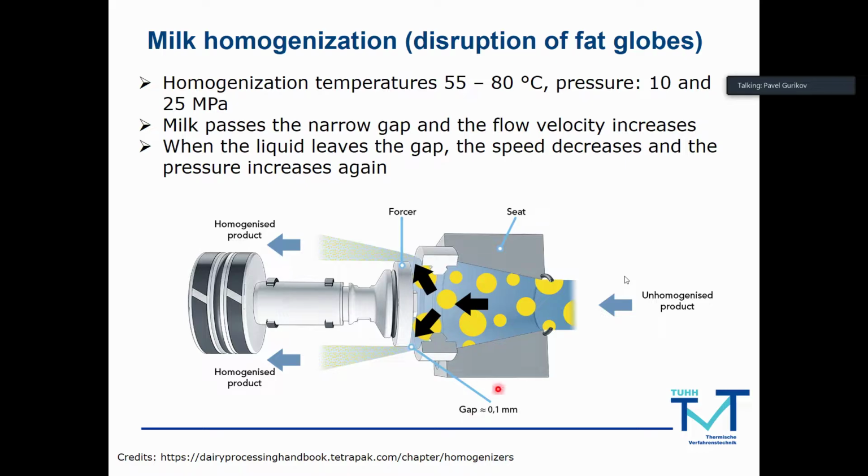So what you do when you pass this liquid through such a small gap, you create very, very high shear forces. So basically, you apply forces to each droplet so that you shear and break them down. And under certain conditions, droplets not only get kinetic energy, so they don't only start moving faster, but they also experience what is called breakup. And then you get smaller particles.